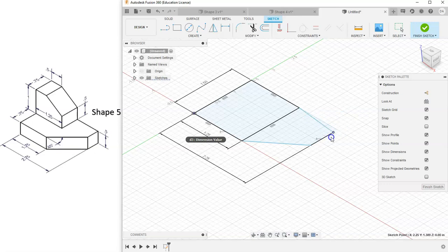And it looks like we didn't fully constrain this line. We didn't give it a horizontal constraint when we built it. You might have actually. Yours might be black. It looks like I just missed a constraint when I was building it. It didn't magnetize perfectly. Maybe it was just like that. It was almost horizontal. I don't know. And like I said, yours might be horizontal already. But how do we fix this if this happens to us?